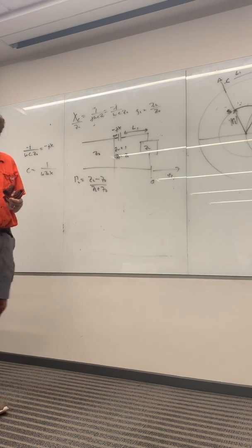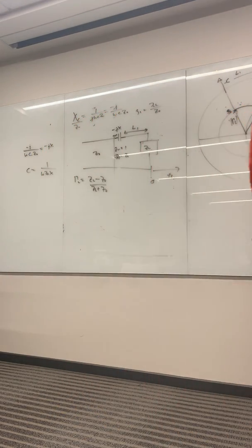Now, getting back to the problem that he's talking about, is it 32 or 31? 35? So this is going to be problem 2.35. A matching network using a reactive element in series with the length D of transmission line is used to match a 35 minus j50 ohm load to a 100 ohm transmission line at 1 gigahertz. So ZL is equal to 35 minus j50, and Z naught is 100 ohms.